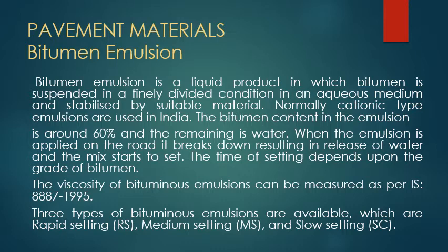Bituminous mix is prepared by using suitable type of modified binders, which we'll be discussing in detail in the next slide, that offer better resistance to deformation at high temperature and remain relatively more flexible and elastic at low temperatures.